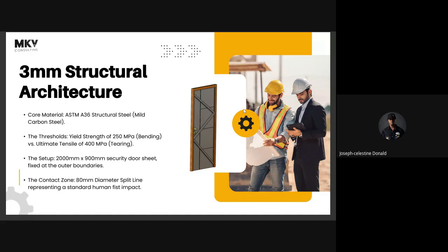Now, the yield threshold of the steel you're using is 250, with an ultimate tensile stress of 400. We saw that whenever you're selecting materials in SolidWorks, you get the ability to choose any material based on its density as well as its yield strength, because like we said, the stress limit is the yield strength of your material.